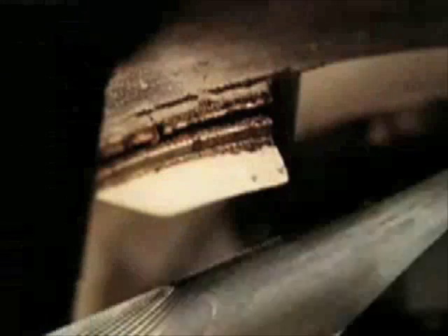It is important to inspect the hub pilots that hold the brake drum in position to ensure no damage is present. Uneven brake drum seating can have a negative effect on the balance of the assembly.